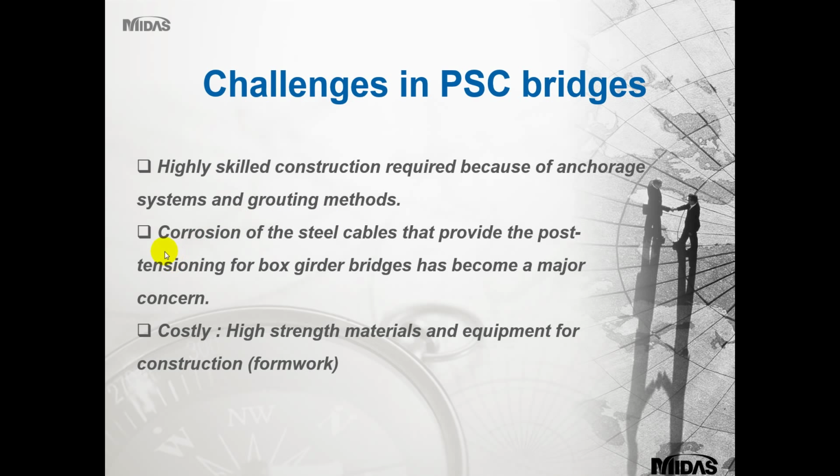If moisture gets in there, it can create corrosion of the steel cables that provide the post-tension for the box girder bridges, which becomes a major concern because then you can have catastrophic failures of the mechanisms holding the bridge up. It can become costly because of the high strength materials and equipment for the construction, i.e. the formwork that is used, and also the grades of the steel that you're using as well.